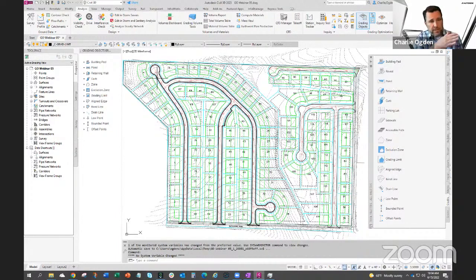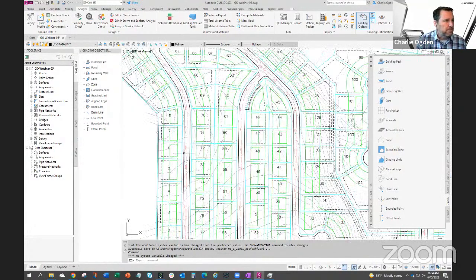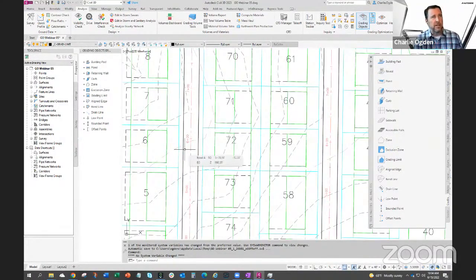The smoothing will smooth out the transition from adjacent triangles to kind of create that similar thing that a vertical curve does, but it's not going to be real vertical curve geometry. It'll kind of get you close. And also, it's not doing perfect cross slope along the road. We'll put in a min and a max, but the cross slope can vary a little.